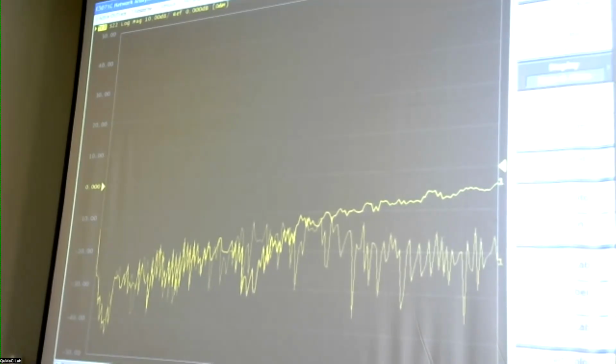So the reflection from this plane is going to be very less. The wave will travel, it could get reflected quite badly out here, but that wave is going to have a round trip through the cable and will get attenuated. If this loss is big enough, then you might not even see the fact that this particular end is badly reflected. So if this was correct, this is still possible, provided you are talking about a system where you have bad reflectors on one side of a network, but the internal transmission is very lossy. So in that case, it's possible.